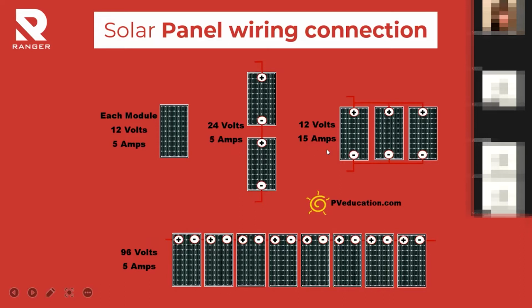Okay, function of this series wiring connection. For example, if a customer wants to use 24 volt output for the load, for example, a barrier. We have a barrier that uses DC 24 volt. So the batteries can be connected by series connection. Then it will give output to the barrier, which is 24 volt. For CCTV, normally 12 volt is enough because the camera normally uses 12 volt only.